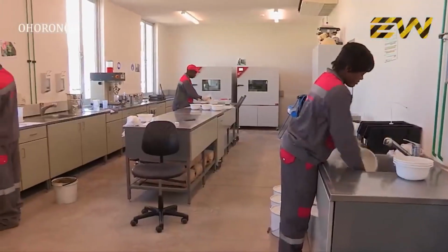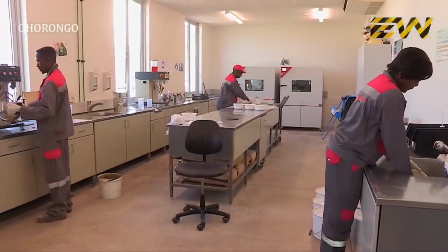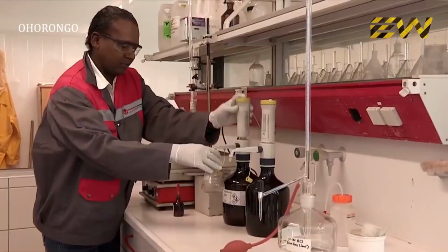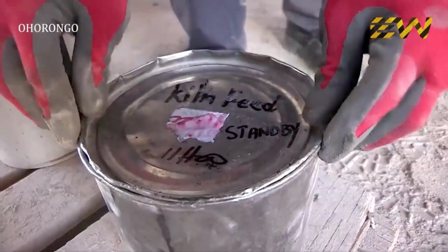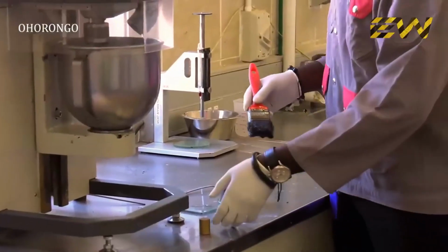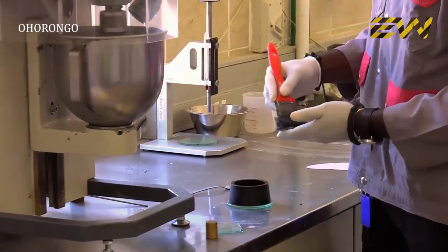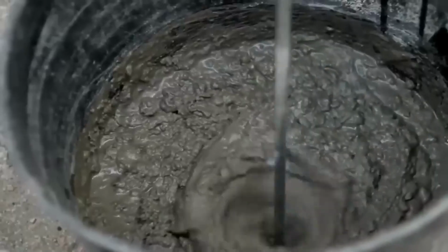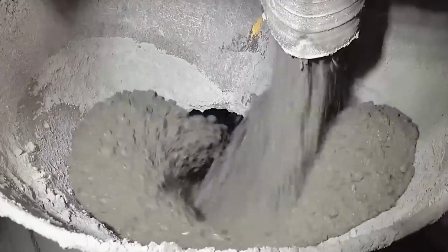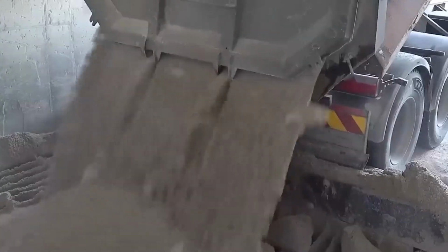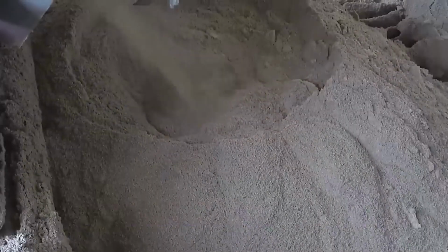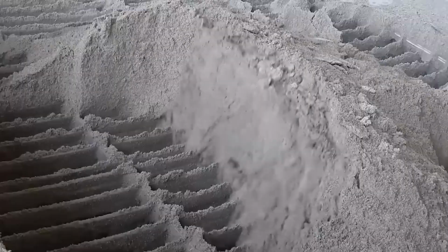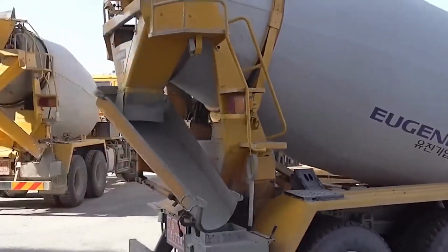At this point, the cement is rigorously analyzed in the on-site quality control laboratory. Technicians run chemical composition analyses and physical tests on the cement to ensure it meets all the necessary quality standards before being approved for shipping. Though cement itself is a key building material, it mainly serves as the binder for concrete. At concrete production facilities, the precisely measured ingredients of cement, water, and fine and coarse aggregates like sand and gravel are combined in mixing trucks.